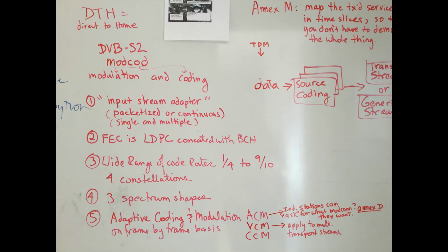Here's a run-through of the DVB-S2 standard. This is what we know so far. DVB-S2 stands for Digital Video Broadcasting Satellite Second Generation. There is a recent extension to this standard called DVB-S2X that has very low SNR capabilities and a lot of other goodies. The GEO project, ASCENT, and eventually the High Earth Orbit project are expected to transmit using DVB-S2X.